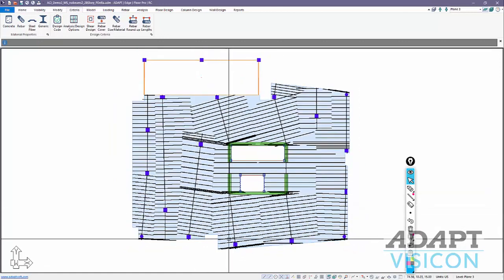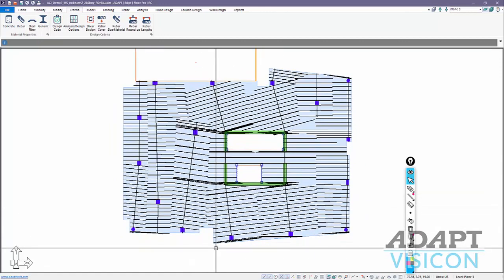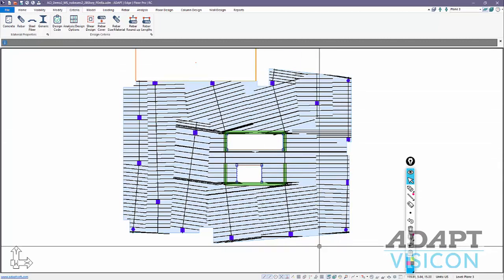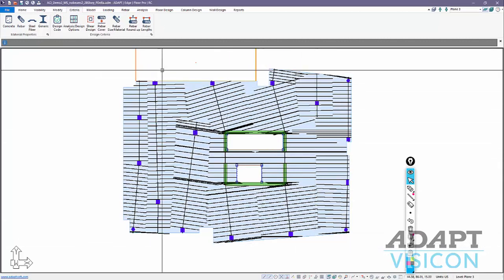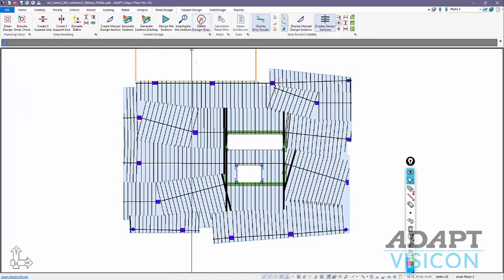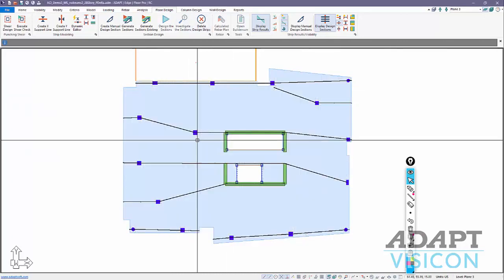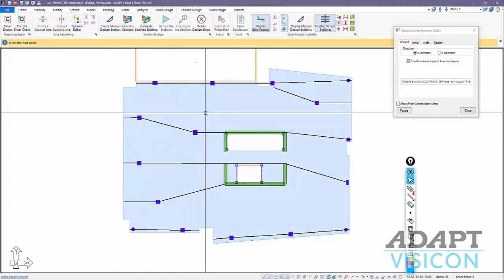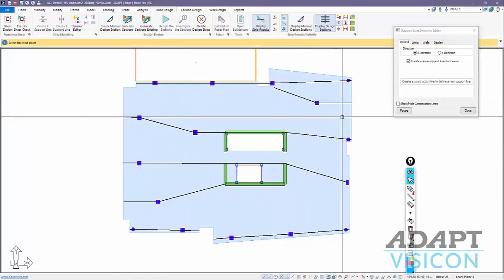So that functionality will likely be restored in a future version, but in this first release, that functionality is removed from the version. So if I, for example, wanted to add middle strips in this X direction, I can very easily do that again using the wizard. I could just create strips like so.